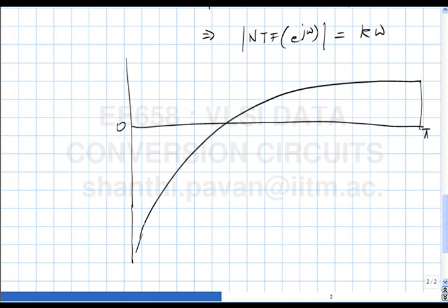All right. Now the new NTF is this, 0 dB, mind you. What should this be then? This is the modulus of the NTF in dB, so this is 20 log to the base 10 of NTF. So what should this be? The out of band gain of this first order NTF is basically 6 dB. Correct? So this is for RC equal to 1.